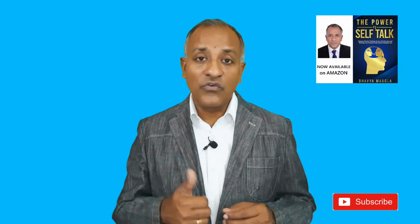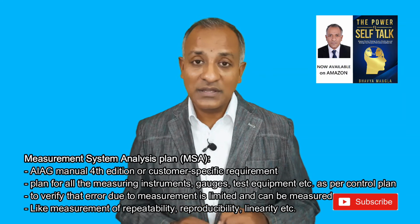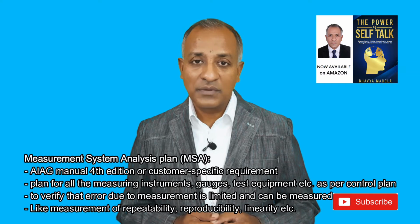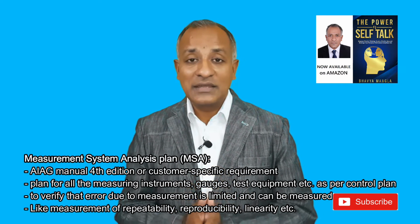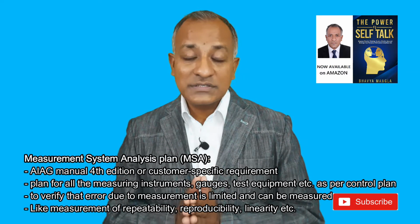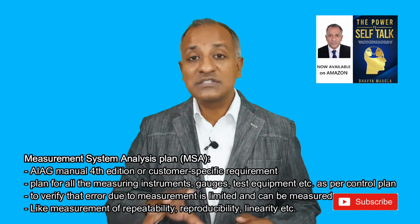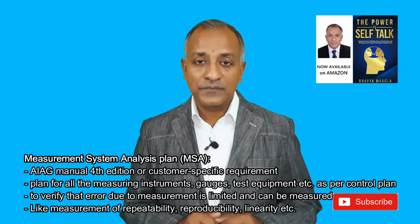Once all these documents are ready, some tangible outputs come. One is in the form of the MSA study, Measurement System Analysis, which is the 4th edition as per the AIAG manual, or it can be another manual which the customer may prescribe. The objective of the MSA study is to see the possible error that can come from the measurement system. As per IATF 16949, there is a requirement that all kinds of measuring instruments specified in the control plan should be a part of the MSA study.